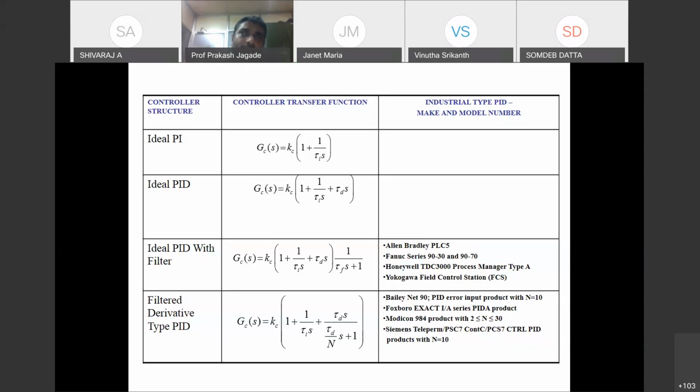It is basically the anticipated error, and you can find that by determining the rate of change of error, de/dt. You will be able to predict the value of error at the t plus td instant. So based on the current error and the rate of change of error, that's what I call an anticipated error or a projected error at a future time.